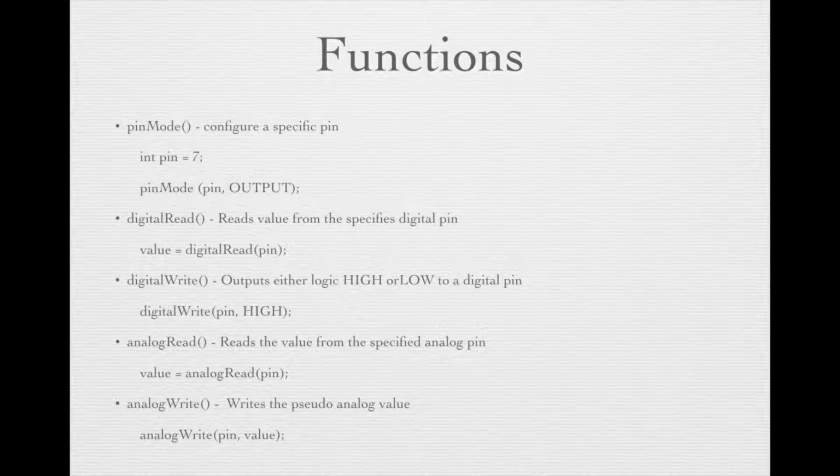There are a few inbuilt functions, and these are a few of the most important and frequently used ones. pinMode. pinMode is used for configuring a pin as an output or an input pin. If the pin is 7, pin number 7 is configured as output.